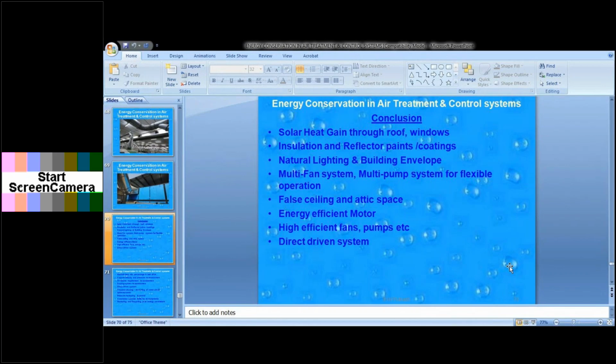Even the wall also. We see this capacity, but the wall will be different. There will be a brick wall of 9 inches, or instead of that, 12 inches. So the coefficient of heat transfer will change for 9 inches and 12 inches. Roof height will be different. A false ceiling height difference of 1 foot will make a lot of difference in the air changes. Instead of 12 feet, some places have 14 feet. With a false ceiling 2 feet higher, your entire volume changes. Because of that, more treated air has to be pumped inside, and more treated air is going outside for a change.